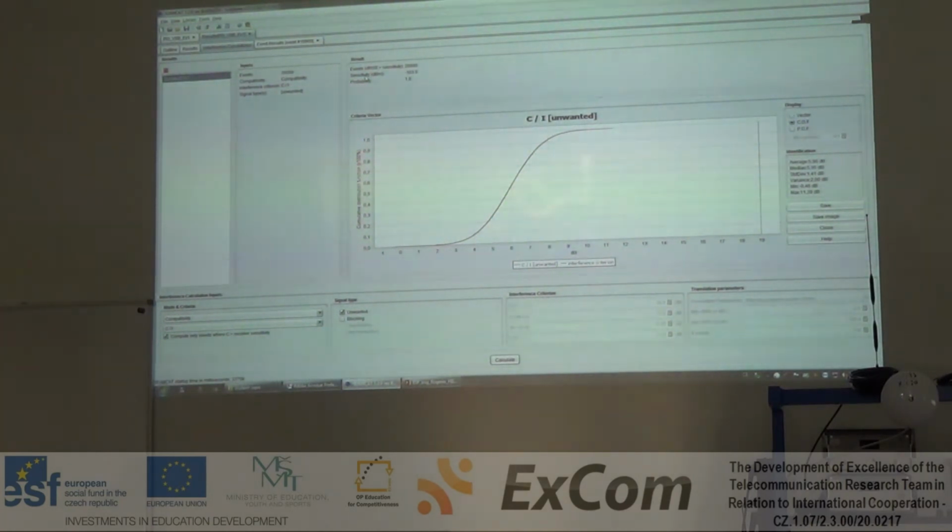Always interfere. This is normal because we are using the same frequency. They are more or less 1 kilometer apart. And one transmitter is 30 dBm, so it's a lot. With free space, there are no obstacles. So actually they are looking at each other. So the receiver will be receiving signal from the wanted transmitter, but also from the other one. It's like hearing FM radio from two stations at the same time. This is what is happening. So is it good? Is it okay?